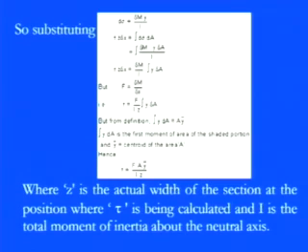So you see how much distance there is of the centroid from this neutral axis. If they are common, then this particular first moment of area just coincides with each other, and we can calculate correspondingly. But here, whatever the distance of ȳ is, the main distance from the centroid to the neutral axis, always comes up in this first moment of area. So with that we can simply put this A into ȳ here, and we end up with the shear stress formula.